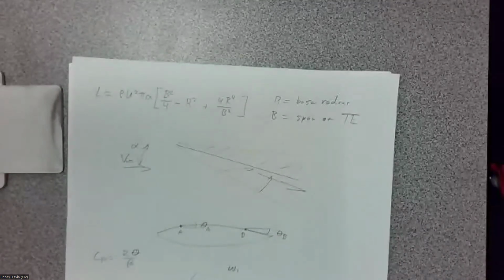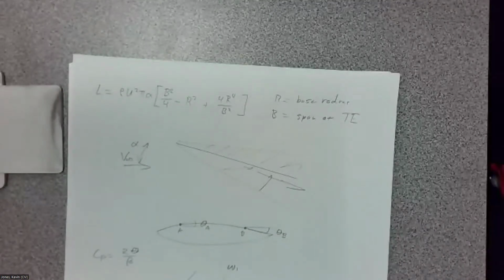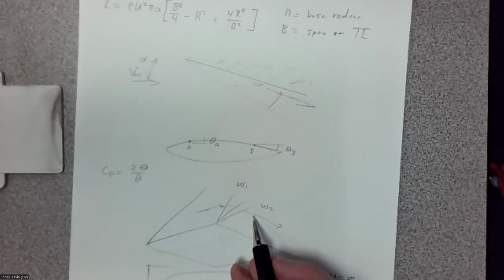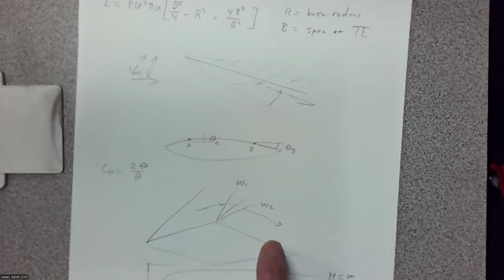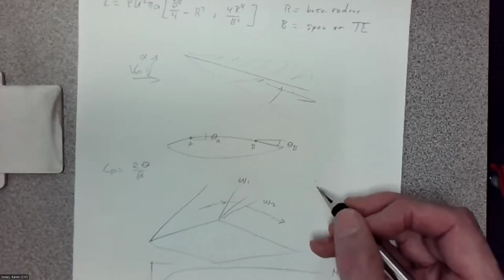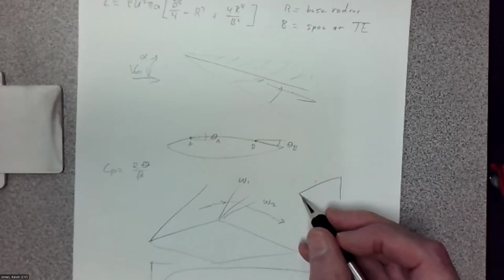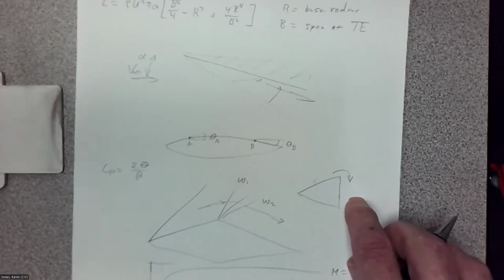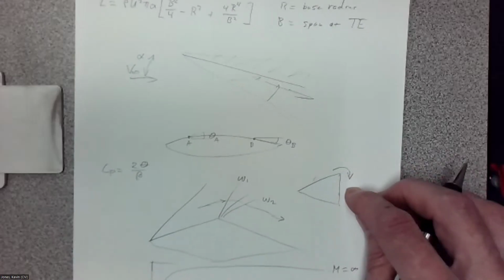So when you start talking about hypersonics, if the Mach number in this region is already super high, you can imagine that we may not be able to expand it all the way to be tangent with this downstream surface. If you have a body that's more like a wedge, and it has to turn really hard, for sure you're going to run into a limit. The flow can't do that.